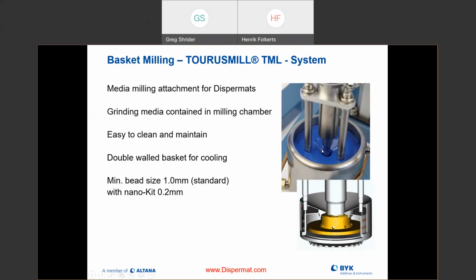That actually is designed to draw my mill base into my milling chamber. And then the beads and the milling disc right here, with the optimized tip speed, will break up these binding forces. And then on the bottom here, I have a screen, and outside of the screen, I have another Cowles blade right here.